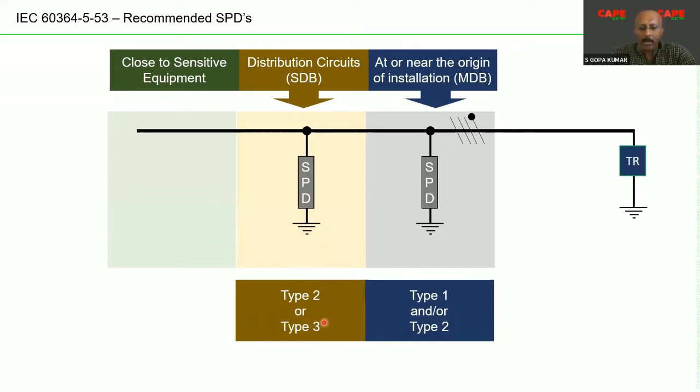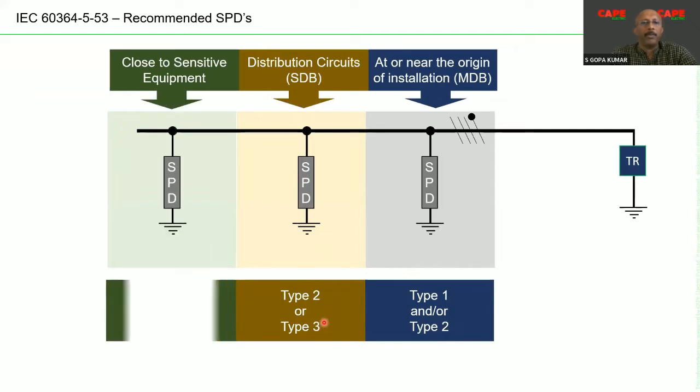It depends on the protection severity you are looking for. Similarly, close to the sensitive equipment, you can also go for a type 2 SPD or a type 3 SPD. So basically, this is how SPDs are selected and installed in the electrical network.